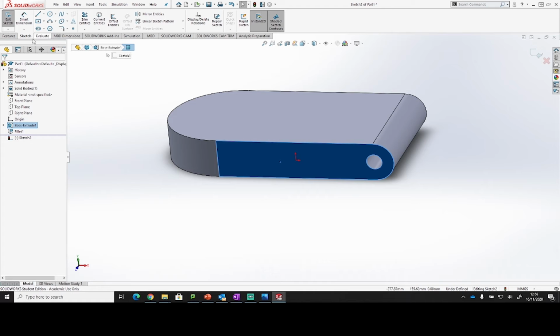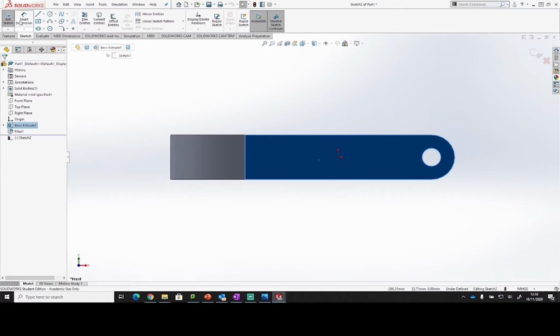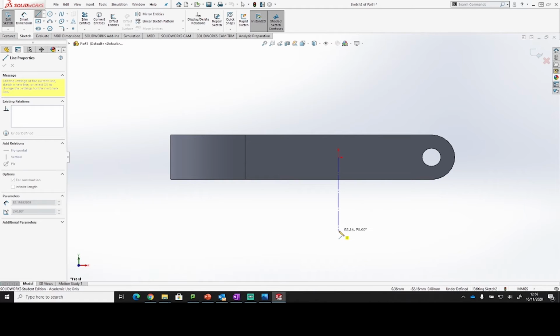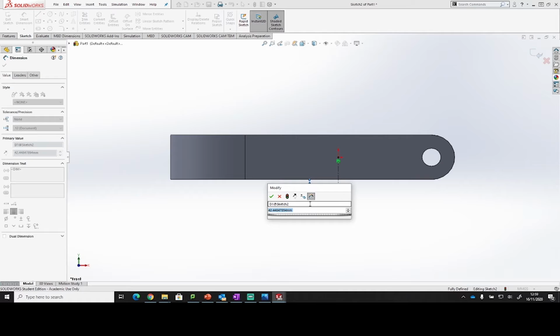And by sketching on that outside, if I turn to that side view, I can create a center line coming down from my midpoint or my origin to the center position of where I want my circle to go on the arm. Now, what that position is going to be from there to there, being 36.5.